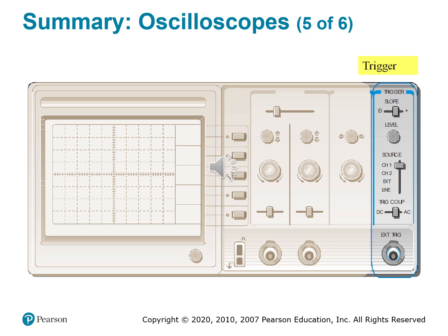The trigger synchronizes the signal so that each cycle starts at the same point. And that allows you to get a stable, repeatable display. Let's go ahead and walk through the controls. So first you have the trigger slope, which is plus and minus. This tells the scope to trigger on a rising edge or falling edge of the waveform. So use rising edge when you want to capture signals going up, and falling edge for events that drop down.